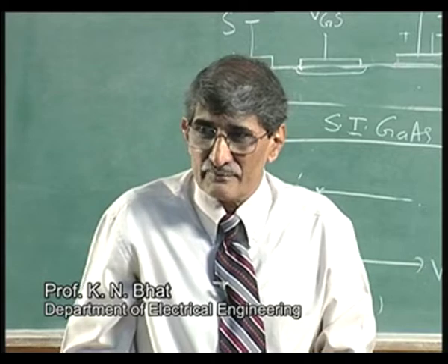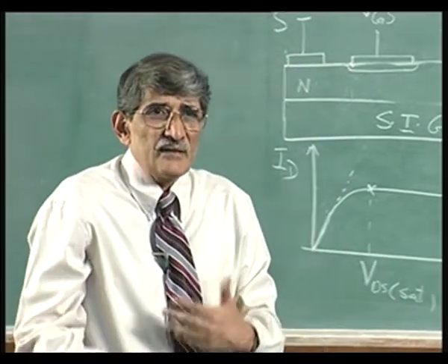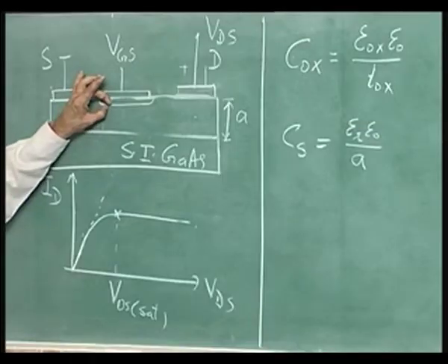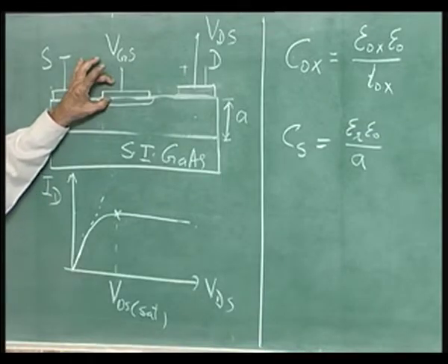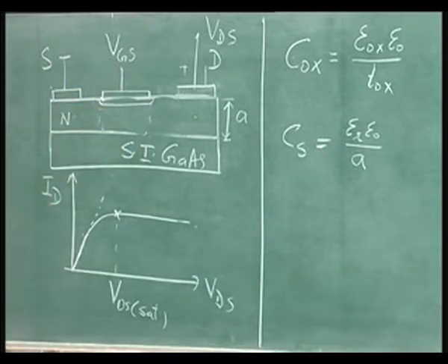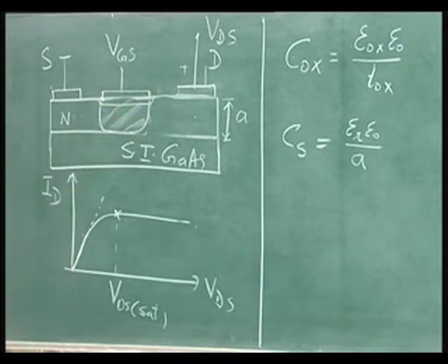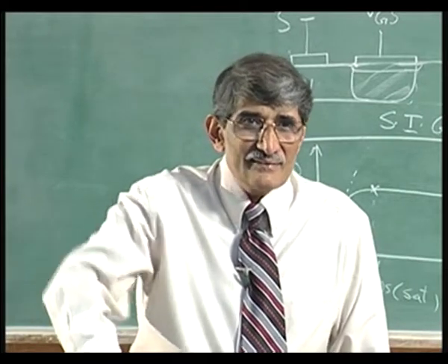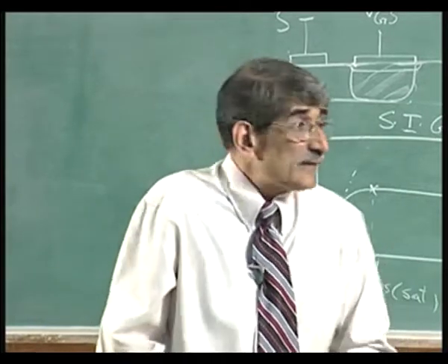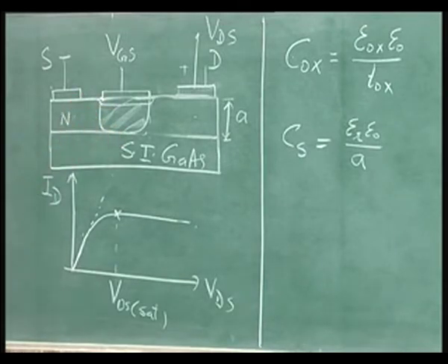without any gate voltage. So, to turn off the device, these are terminology which have been beaten up so many times. To turn off the device, you must increase the gate voltage negatively, so that the depletion layer comes off completely like this. When the depletion layer comes off like this, the channel is closed. It is like closing a valve at the inlet of the fluid flow pipe. There is no output.